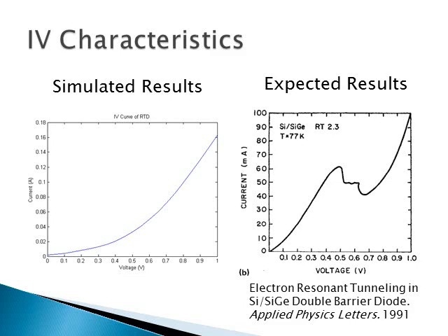Unfortunately, the simulated results did not match well to the expected curve, with no evidence of a negative differential resistance. This could be due to the weighting of the transmission parameters that was used to account for the density of states in the Fermi-Dirac distribution. The more likely cause of the error is the discretization scheme that was used to simulate the equation.